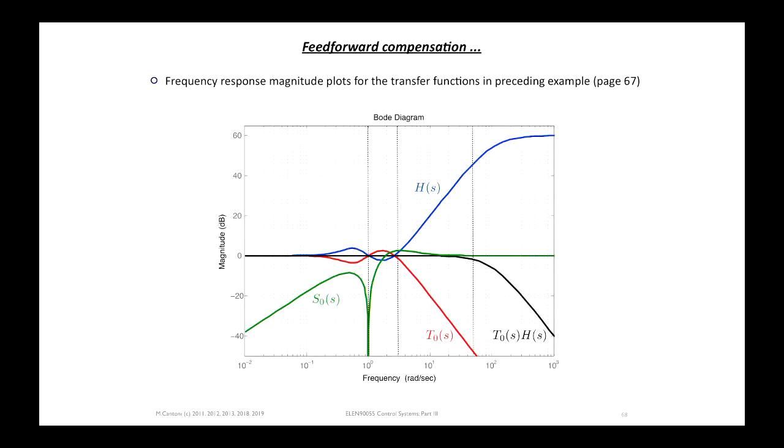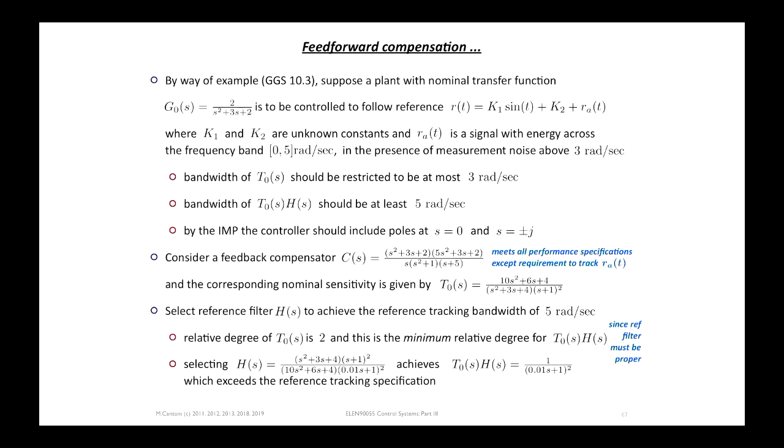But that's the basic idea. But you've got to be careful using this, because what we're doing is inverting a model, and the model will be wrong, and so your inverse will be wrong, and you won't get exactly this flat thing when applied to the real system. But it is a way of introducing an extra degree of freedom to help you manage a trade-off between competing objectives that can't be completely separated across frequency, put into different frequency bands.